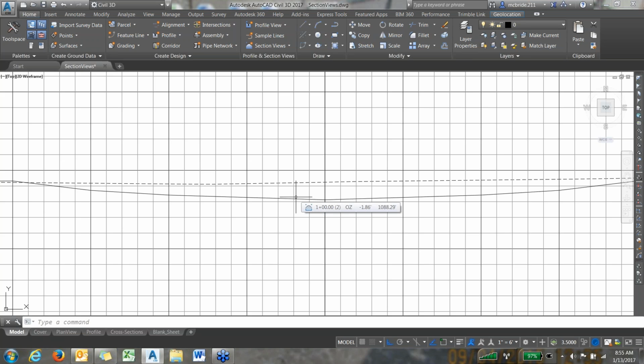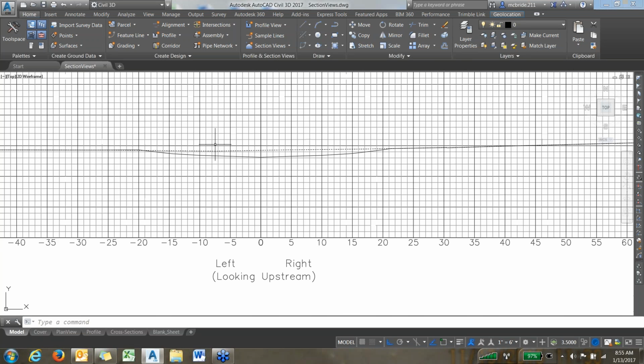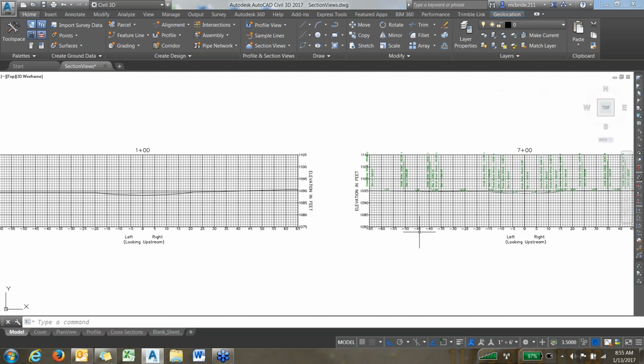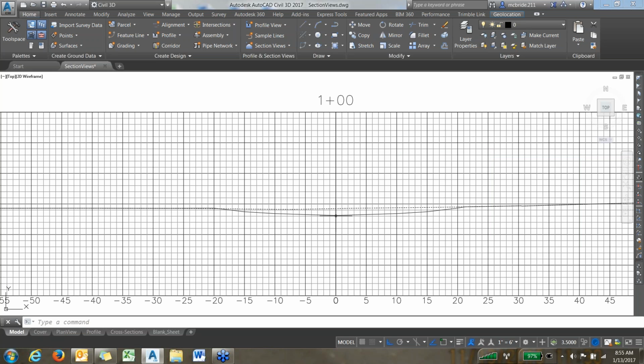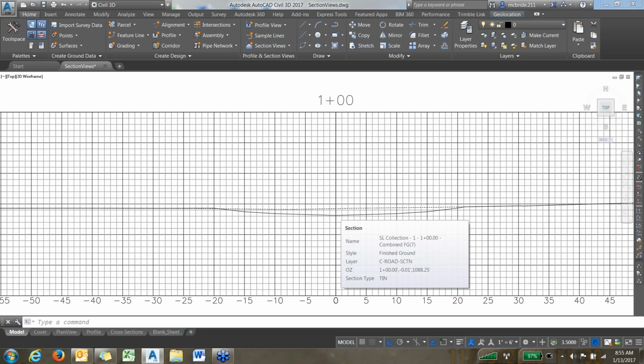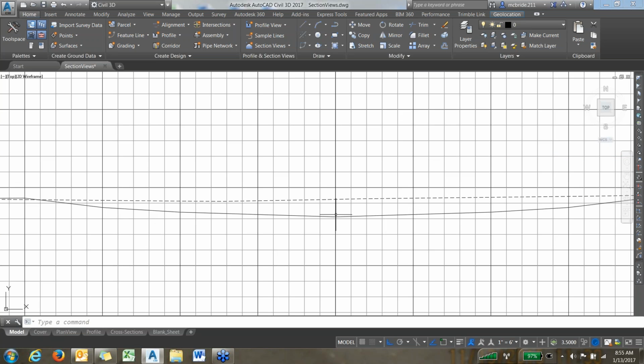So now I've created a cross section. And I could do those steps, I could delete the lines over here and get them all nice and neat, but I'm just going to focus on this one for right now so that I can kind of explain what the next step is. This cross section doesn't tell me much. Again, because it's a one-to-one scale, it would be hard to get the exact elevation from the bottom of this cross section. Okay, I can't really tell. This small square right here is 1 foot. Okay, so where is that? Is that 1.1, 1.2? I don't exactly know.